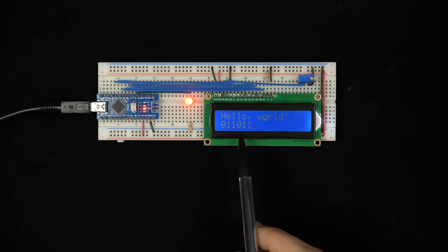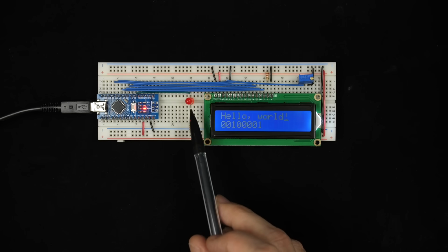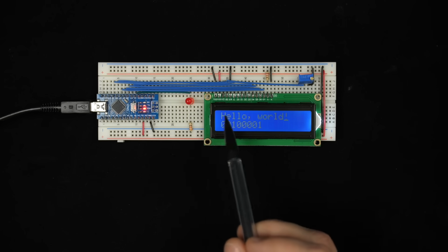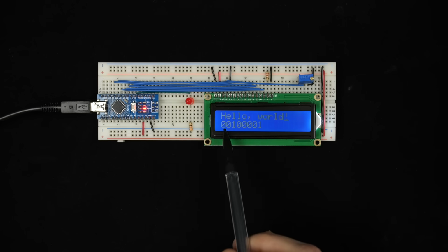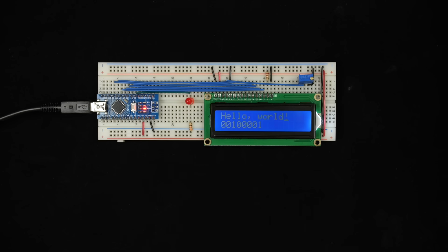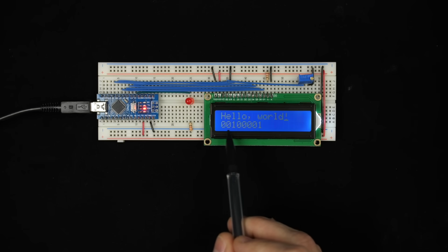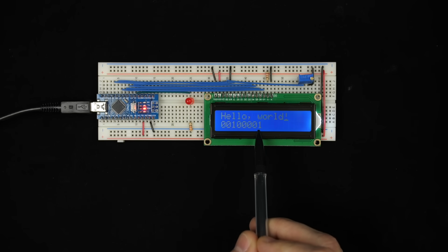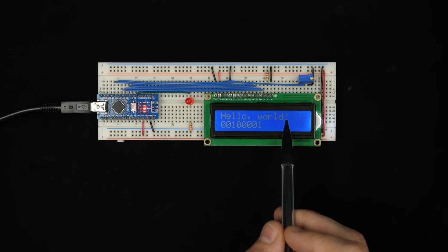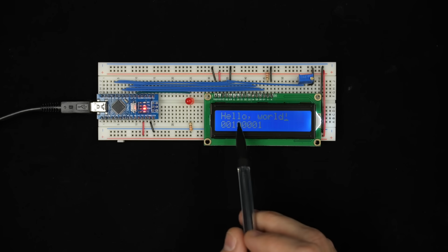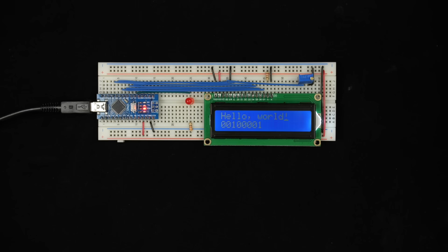This should be easier to keep track of because when it outputs a 0, the LED should be off, and when it outputs a 1, we should see the LED on. So even if you don't have an oscilloscope, if you slow the clock down a bit, it should be fairly straightforward to match this up and verify that it's doing what we expect. And once you verify that it's outputting the right bits, you can also look at this value. This is 32 plus 1, which is 33. So the last byte it outputted was a 33, and 33 is in fact the ASCII value for an exclamation point. So you can also verify that. The LCD makes it a lot easier to both see what's going on as well as troubleshoot this.